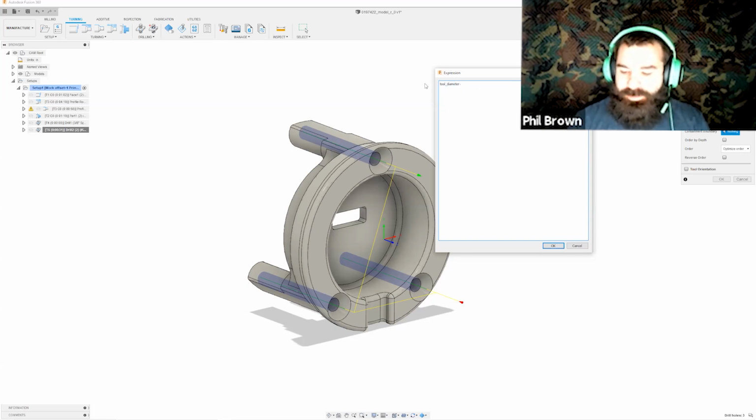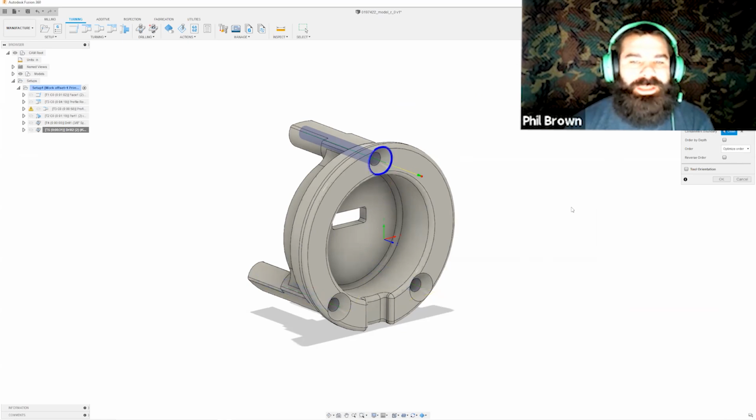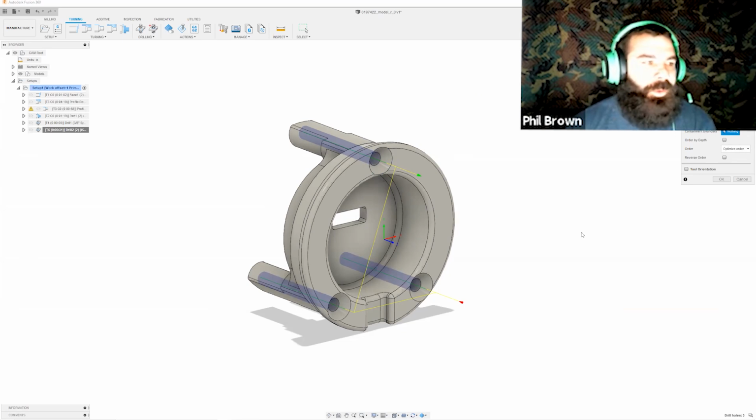And I want to take 3 thou undersize. So I'm going to go -3 thou inch, and it's going to give me my lower threshold point. I did the same thing for the upper threshold point, which would be +3 thou of an inch. And as you can see, it actually pulled all 3 of those holes. A neat thing I could lastly do, in the event that I want to work in a certain area, is give that a specific boundary area and it will automatically narrow down to just one hole.